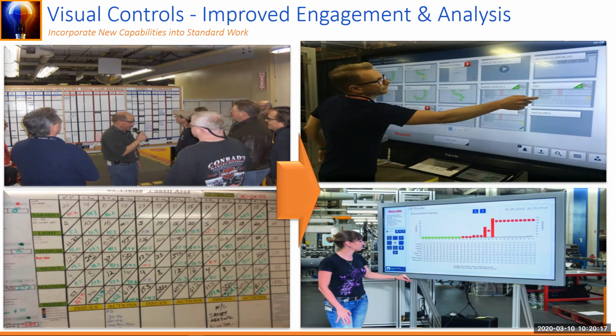A great example here is customer Unilever. We implemented what we call TPM Tuesdays. Within the organization, every Tuesday, we actually stopped the line and utilized the data coming from the system itself to improve the process. We looked at what the top 3 failures were over the past week, and we said, what is it that we can do today to improve one of those reasons for downtime?